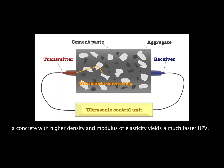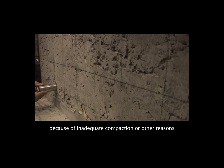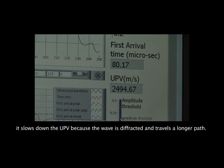High density and modulus of elasticity yield a much faster UPV. When concrete contains large void or honeycomb because of inadequate compaction or other reasons, it slows down the UPV because the wave is diffracted and travels a longer path.